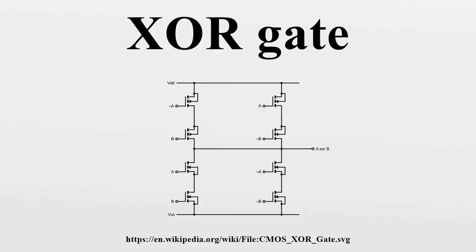More than 2 inputs. Strict reading of the definition of exclusive or, or observation of the IEC rectangular symbol, raises the question of correct behavior with additional inputs. If a logic gate were to accept 3 or more inputs and produce a true output if exactly one of those inputs were true, then it would in effect be a one-hot detector. However, it is rarely implemented this way in practice.